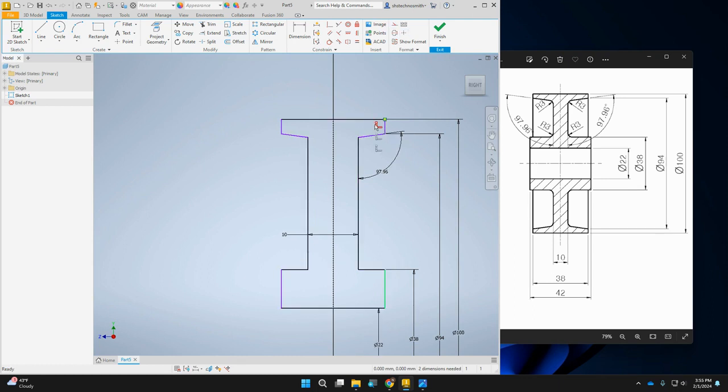This looks like I still got one more. They're still moving. This one here is also still moving. So now this one moves on its own, and this one moves on its own. Right? So that's how we can get rid of some of those constraints that get put on by Inventor that I don't want. If you can't figure it out, we just delete this and start over again at the top and make sure they don't line up.